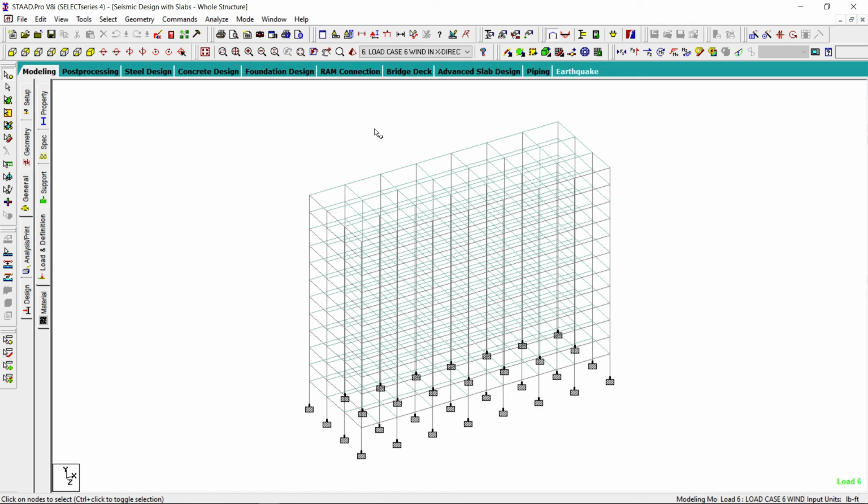What are the additional requirements when we shift from seismic category A to B, B to C and C to D. That is very important. This is all related to seismic detailing. This is a simple ordinary building lying in an aseismic area, so we just have to comply with the ACI 318 code.